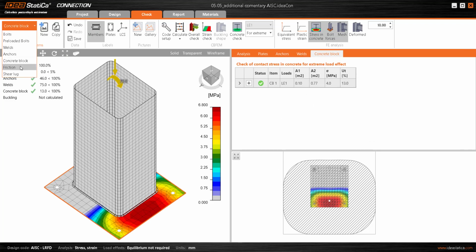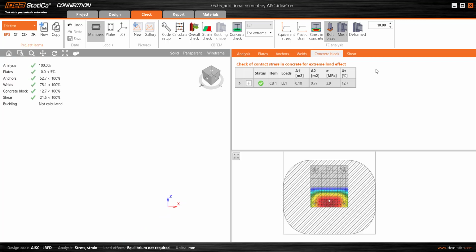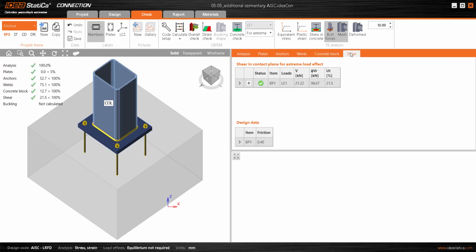Now, if the shear force transfer mechanism is not via the anchors, instead is via friction, we see that it's a bit different. The shear tab appears, as we've seen before. The only interesting difference, in terms of the European standard, is that the software straight away works with a resultant force. The shear resistance is calculated, as we see here.